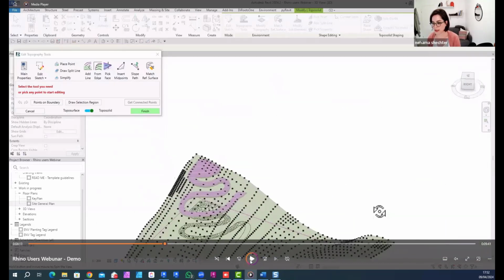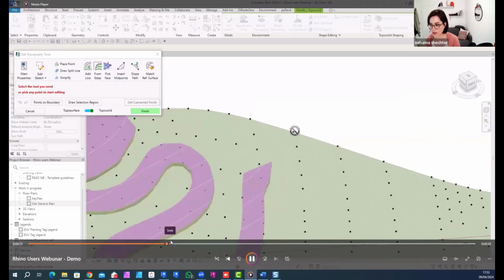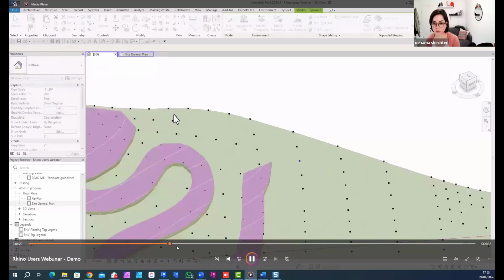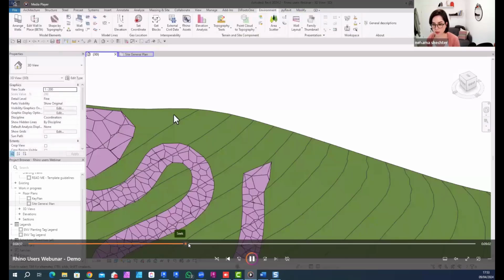And this is where it's a little bit different from the script that you showed, because environment is kind of regenerating the points. Basically the rule is that it optimizes the placement of points to get the maximum accuracy of the original surface, rather than just defining a grid of points. So that's a little bit behind the scenes, and you can see that at each point you can select it and edit it, change the elevation, get all the information, and yeah, it's pretty heavy. And so these pavements over here are also toposolid. So let me fast forward a little bit.